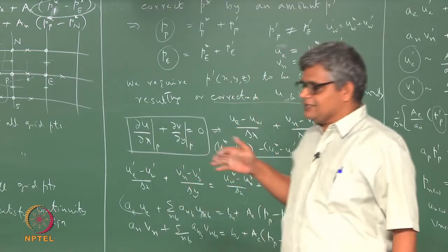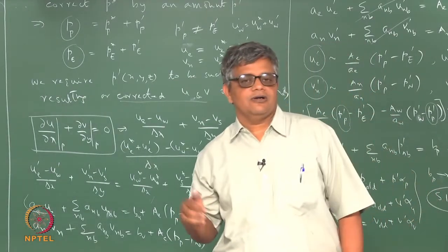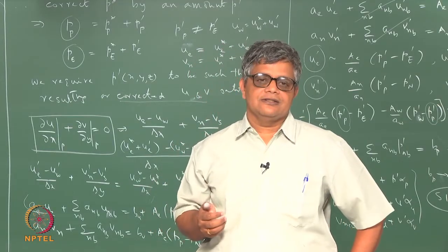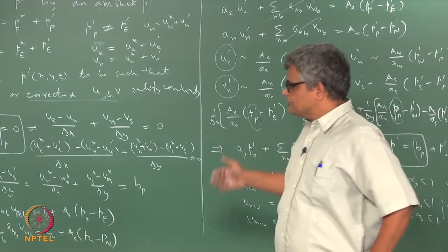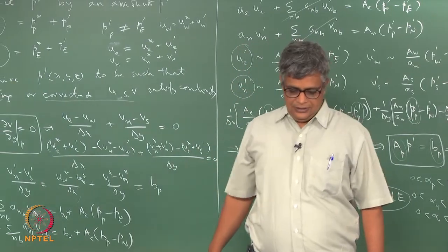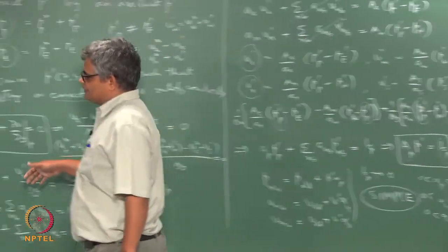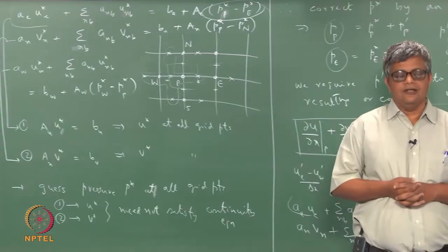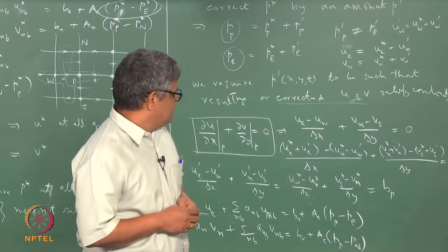So this is a strategy which has worked very well for a number of incompressible flows, and not just fluid flows, but also including energy, including reactions, and including lots of other complications for multi-phase flows and those types of things. Also a similar kind of strategy has been used, and although this method has been developed primarily for incompressible flows, it is also possible to take account of compressibility, compressible flows. And although we have explained this method for a staggered grid, it can be extended to non-staggered grid, but it requires some additional special way of evaluating the velocities.